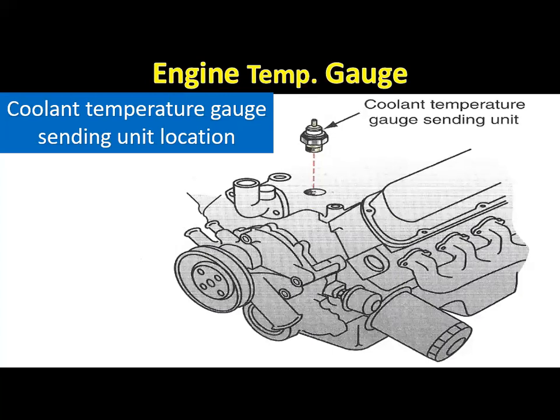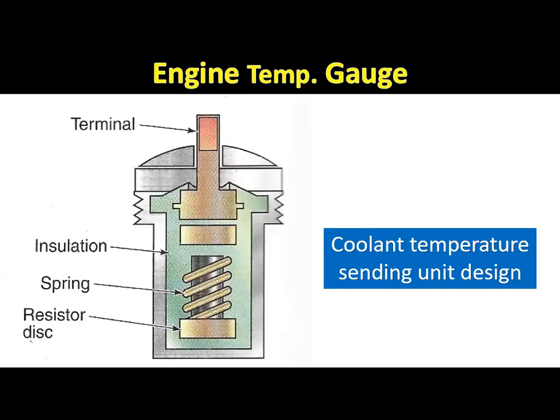The temperature sending unit is threaded into the opening in the cooling system. This sending unit is often mounted in the top of the intake manifold or in the cylinder head. The lower end of the sending unit is in contact with the engine coolant.